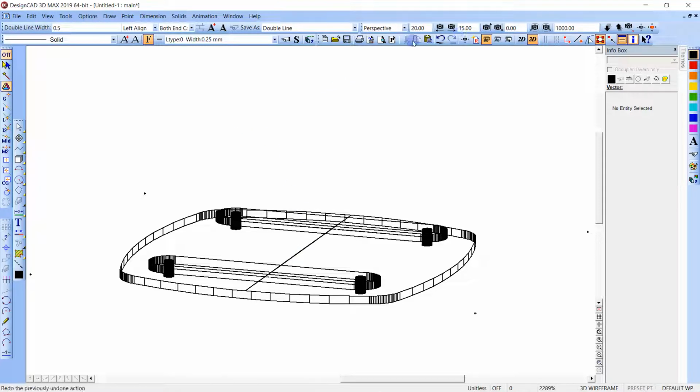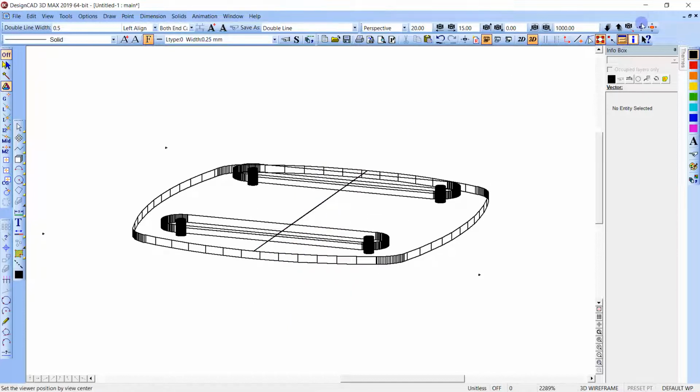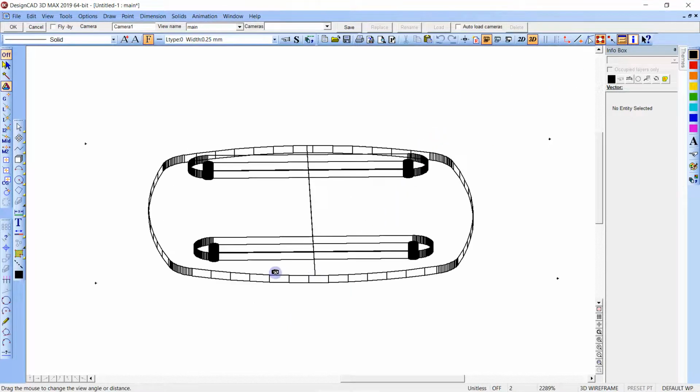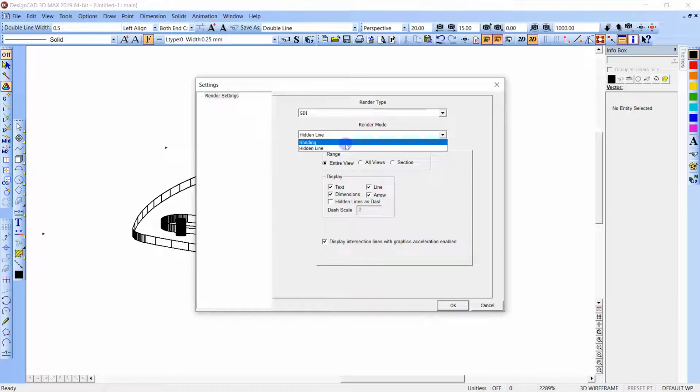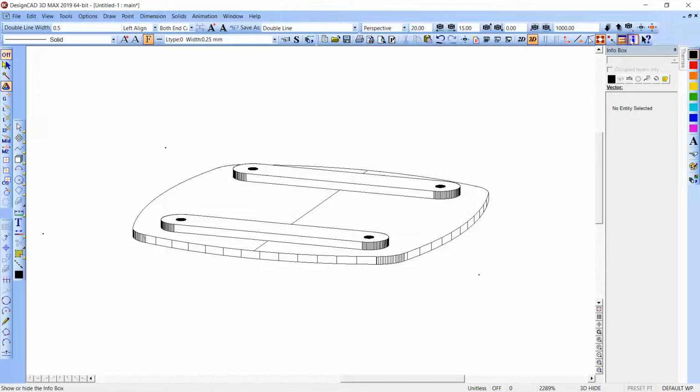So what we want to do is look at menus, which got bounced around here a little bit. So right here, select viewer points. I'm going to select Control K. Actually, no, I'm going to select the middle, enter. Now it's orbitable, right? It's from the center. Escape, and then what we'll do is change it to medium, hidden line, shade, hidden line's fine, OpenGL, and that's fine, okay? And we'll be able to see that it's a 3D part.